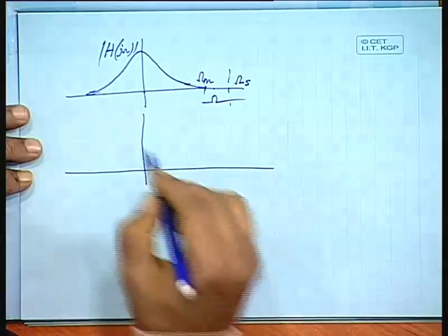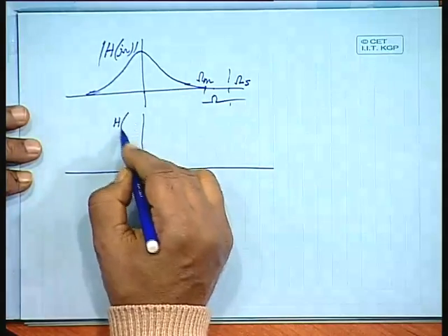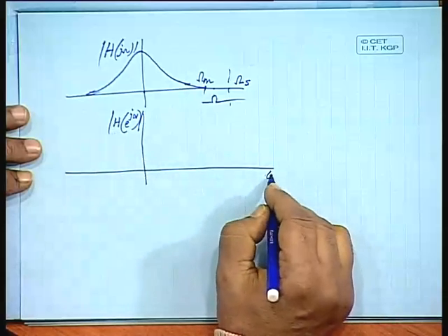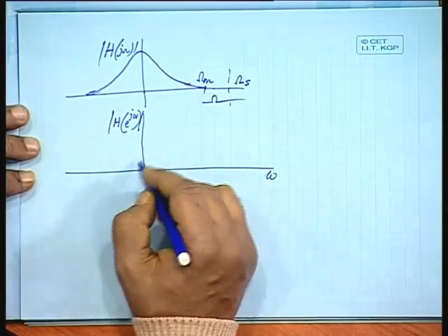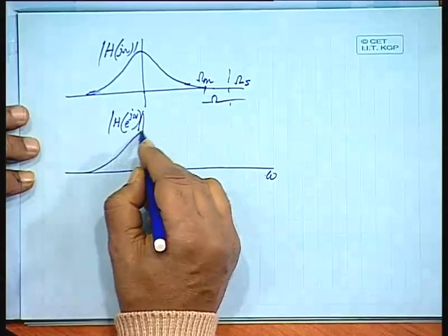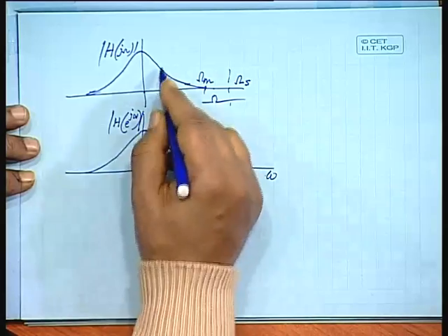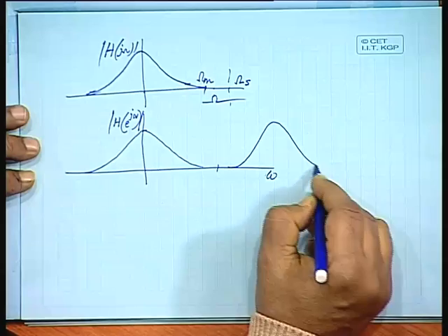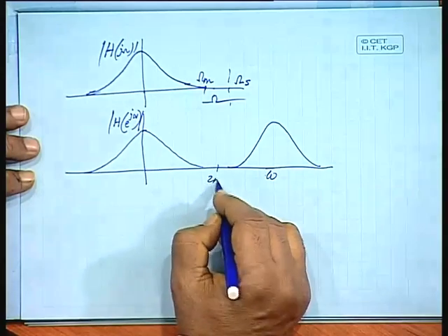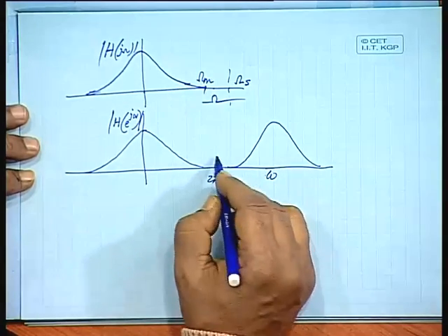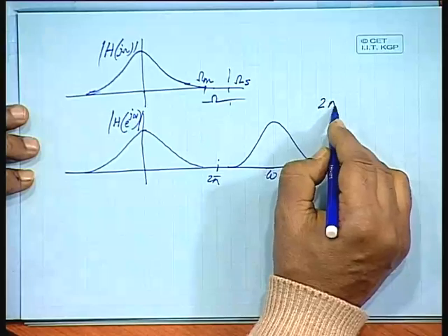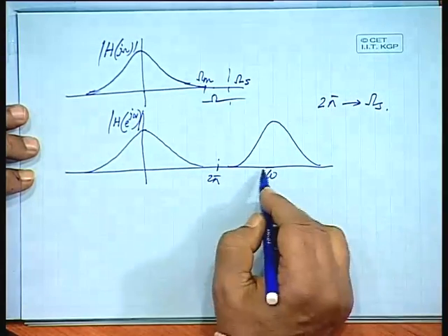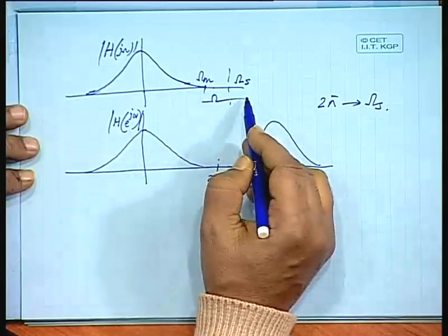the frequency domain response of the system for discrete time systems as a repetition of the same characteristics with a periodicity of 2 pi, where 2 pi corresponds to omega s, the sampling frequency. Okay. So, it is in terms of radian frequency, this is in terms of radians per second.